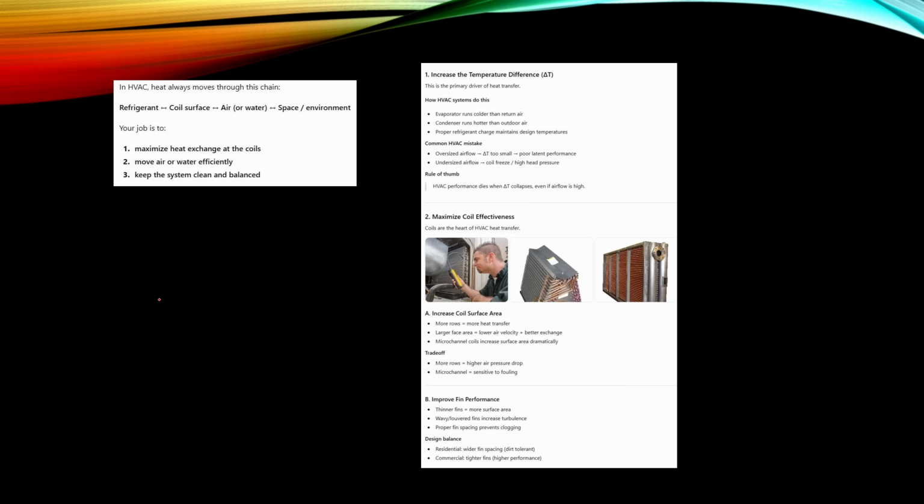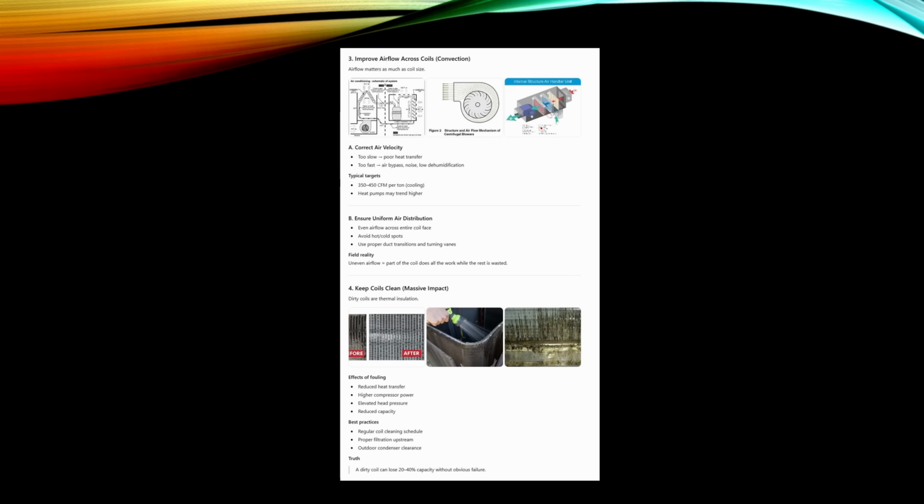Then we need to take into account that those fins will add pressure drop on the air side, and also increase the risk of deposition, and it's not so easy to clean the unit if there are fins.